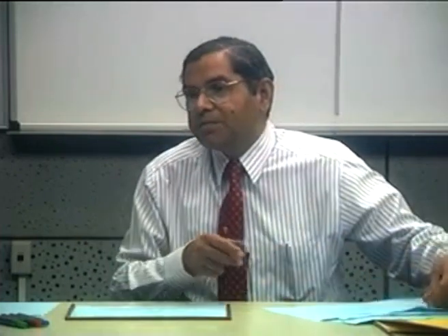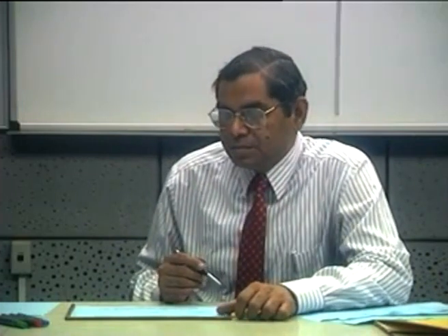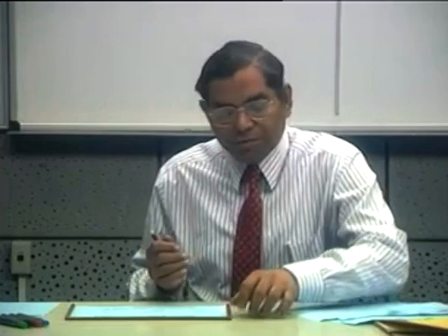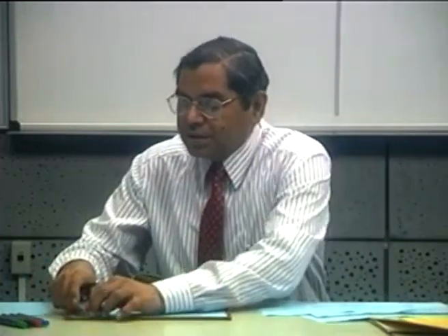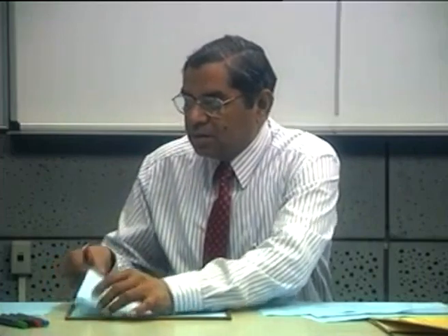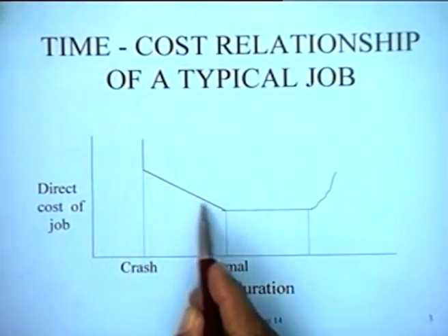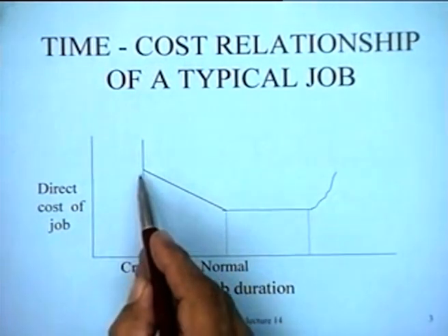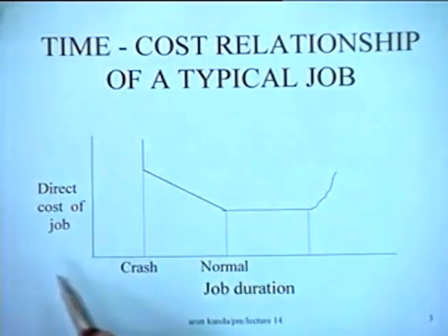Yes. So how the direct cost of the job is going to increase if we delayed it unnecessarily? You are referring to the previous graph. Okay, if you look at the previous graph, for instance, we have said here that this is the best manner in which the activity is accomplished between the normal and the crash duration.